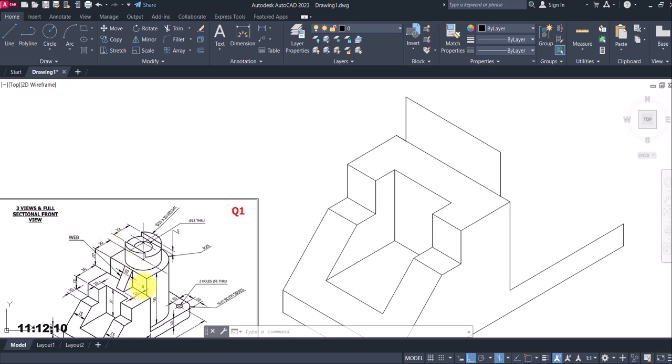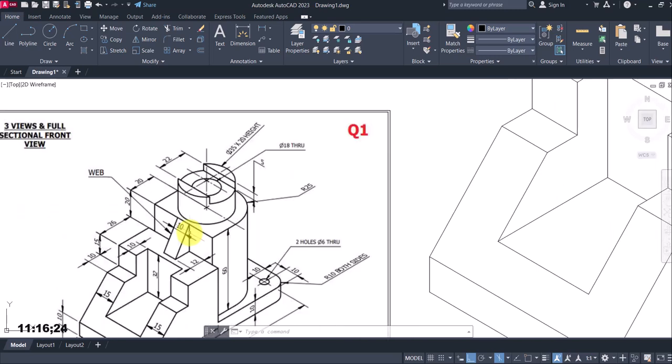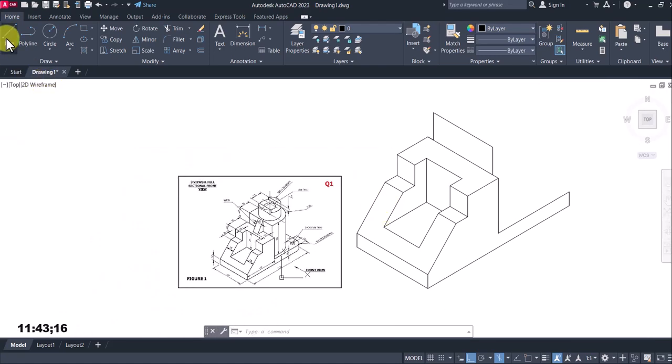I'm going to do a little bit of calculation. The thickness of this wedge is 10, so I want to centralize the wedge. From here to here is 50, so to get to the middle, that will be 25. Then if I do another 5 to make 30, I'm going to get to this end. So from here to here will be 30: 25 to the middle, then 5 will take me to this end. So I'm going to do that.